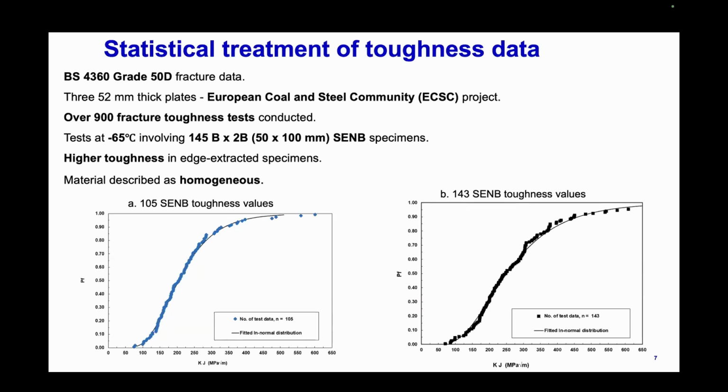So we're just taking one of those data sets, which is the 145 data set. And out of that, the rule for the minimum of 3 equivalent is also that the material should have the same macrostructure and should fail by cleavage. So first, the data set we look at is, out of this 145, 105 of them failed completely by cleavage or brittle failure. So we plotted that on our log normal distribution, and we can see there's a good fit.